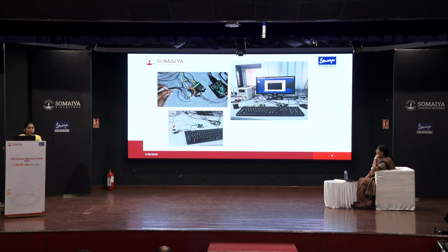These are some real pictures of our project where we have already interfaced the BLDC motor, and we have controlled the BLDC motor speed with the help of a Raspberry Pi controller and the driver. We have also interfaced a few sensors along with the BLDC motor. So with the real-time data of the sensor, we are able to control the speed of the motor.